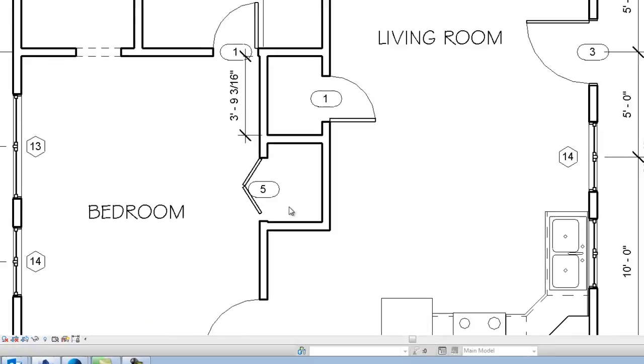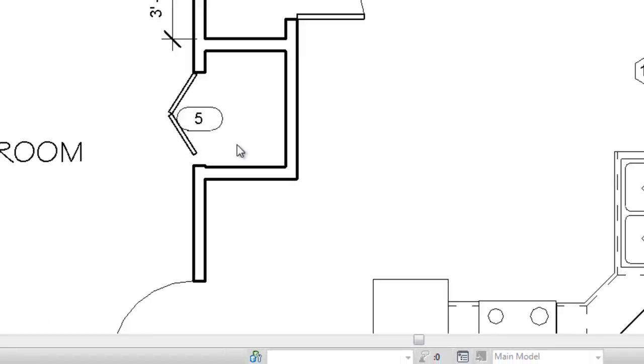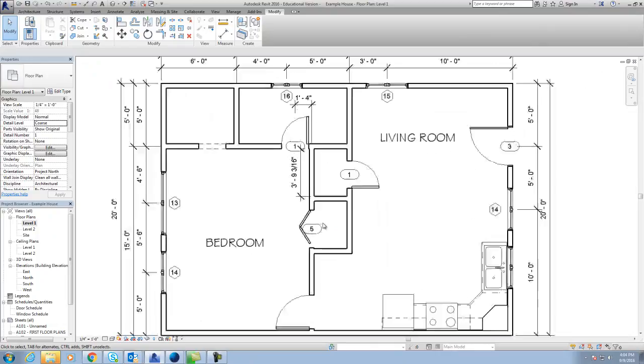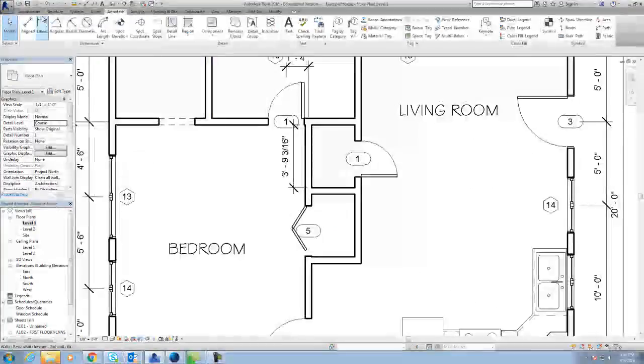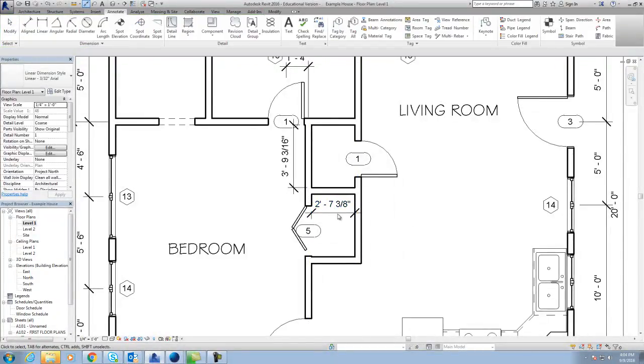Now, in your chapters 7, 8, and 9, you're going to see a lot about bathrooms and clothes care centers. And something you've got to think about too is these closet spaces. This is a closet space. Now, they have to be at least 24 inches interior so that you can hang clothes up. And this one meets that criteria.